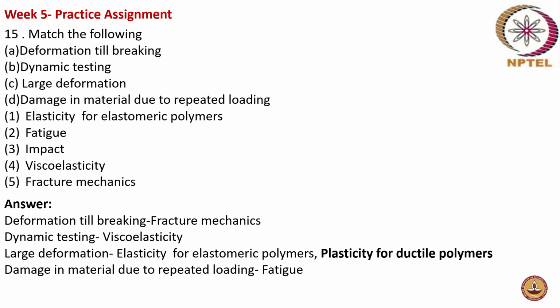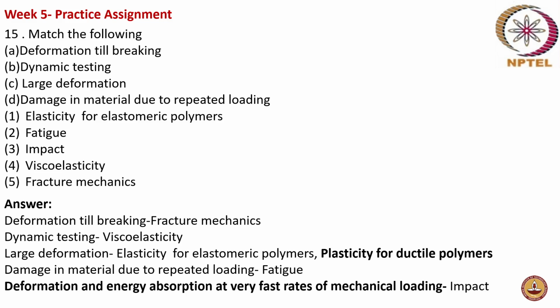And then damage in material due to repeated loading. So due to continuous loading, it need not be the breaking stress or ultimate stress or anything, but some stress due to repeated loading may lead to fatigue. And then deformation and energy absorption at very fast rates. So instantaneous, very fast energy absorption and deformation rates of mechanical loading is nothing but an impact.